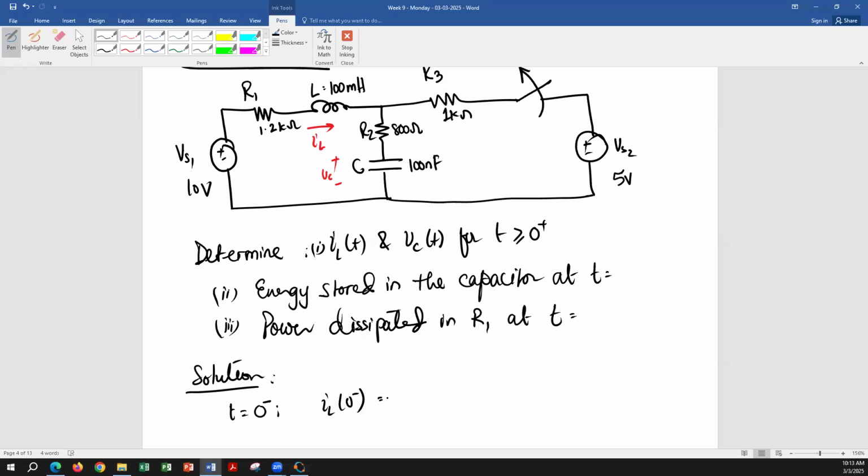KVL is going to give you the same equation. It's not incorrect. That's the equation for KVL, and you can get the current using that equation. But start easy. Don't jump to KVL or KCL if it's Ohm's law.